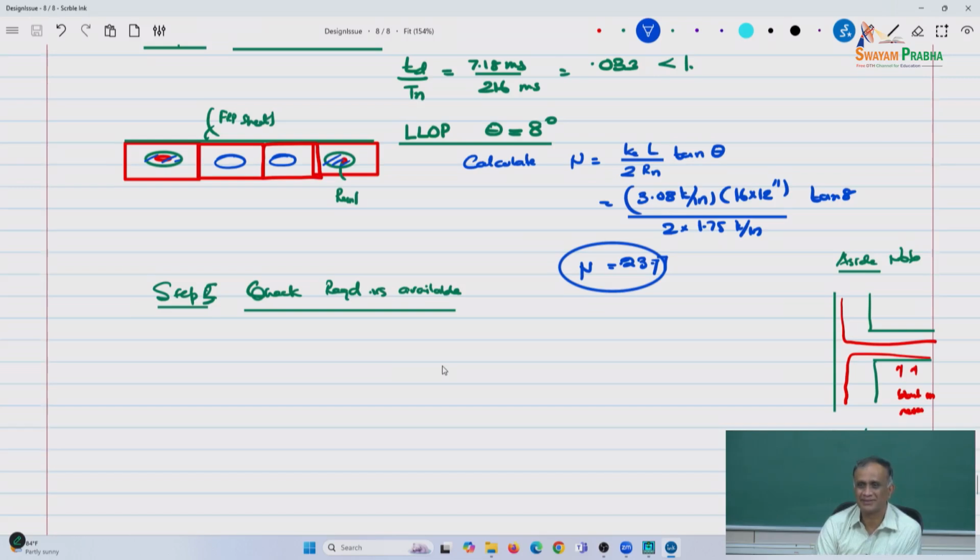It definitely helps in strength, but a masonry wall is not for that purpose. But if you're going to protect something valuable, whatever be the asset inside, that's a consideration to have. If you put a small thin mild steel or aluminum plate, it becomes a composite structure. There are actually designs of composite sections. We can do that. Then you get into composite designs for calculation of your moment capacities.